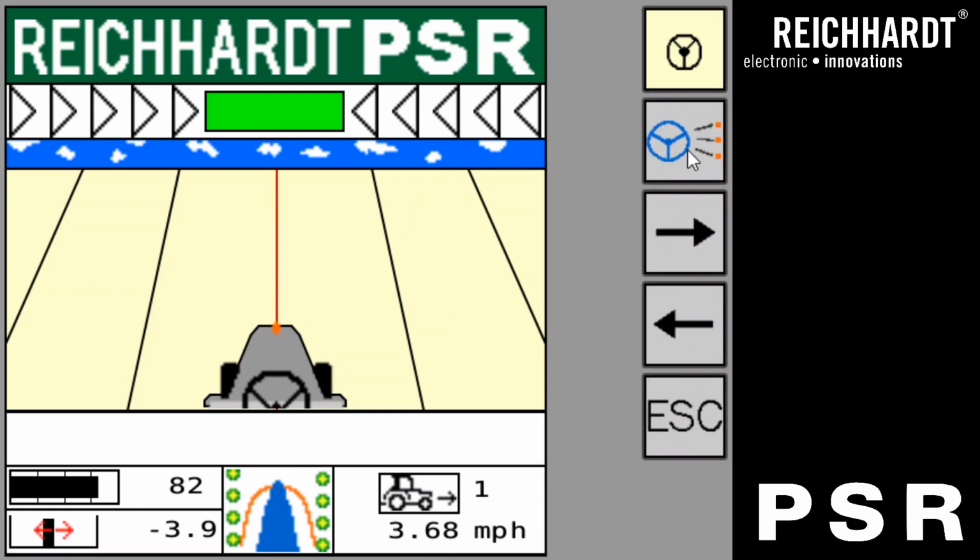and after that it'll move up a few spots, start flashing, and below that you'll have some buttons. Either they're going to be right and left arrows, or if you're running an older software, maybe a plus or a minus. But when you press this, it will change your steering mode in the bottom center, and you'll want to just make sure that you are set for row guidance, which is the corn snout icon, TAC row guidance specifically. And then once you've selected that, just press the flashing icon and that'll lock you into TAC steering mode. Once you're in TAC steering mode, you can then press the wrench icon to go to our TAC configuration page.